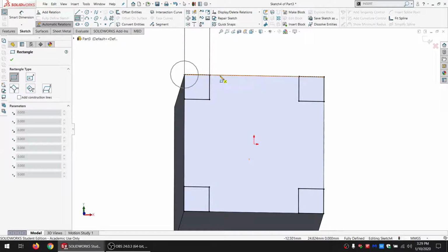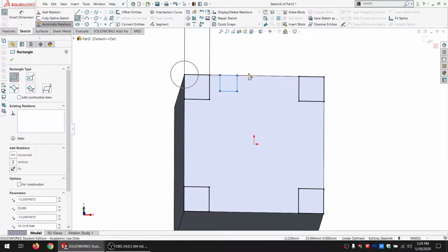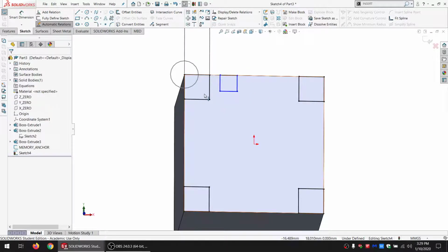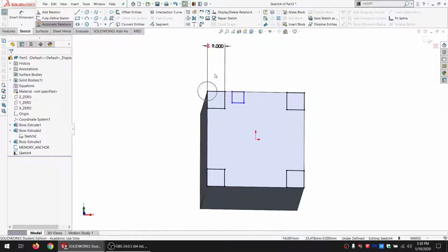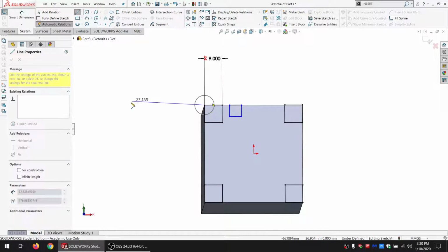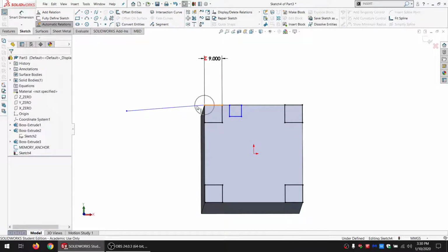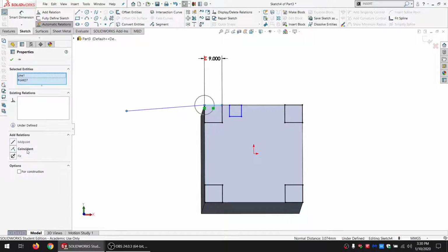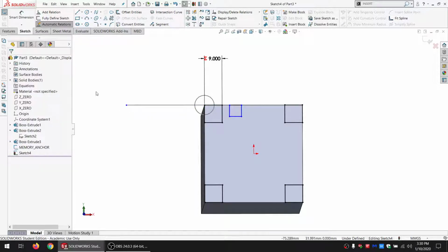So basically we could go rectangle or square, square, square, square, and with this size we could figure out that maybe 3 or 4 of these squares would be the perfect size. But what if we then later on decide, hey, we want this to be 100 millimeters, 200 millimeters, 400 millimeters? Then that doesn't really work anymore. So what we have to do is use a little bit of math and basically force SolidWorks to decide how many. So I'm just going to make this a horizontal line.